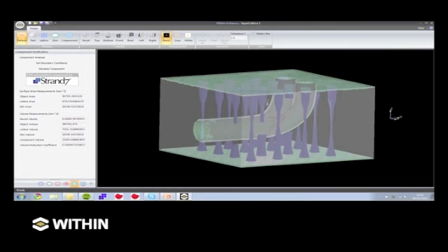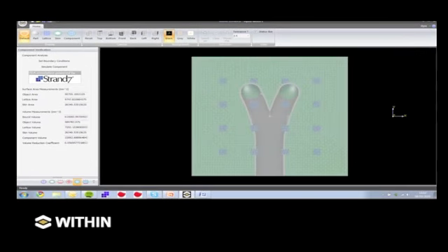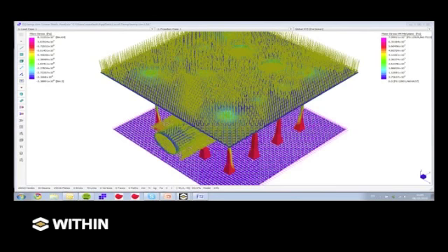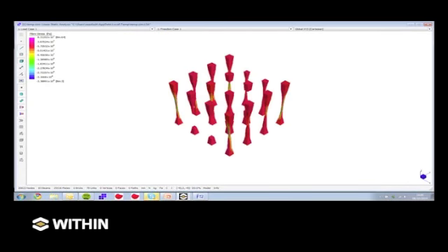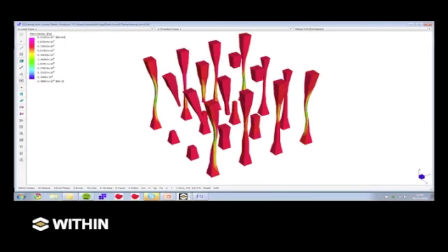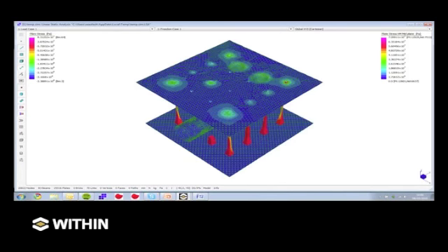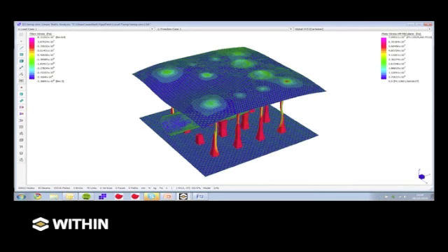So what we do is we can run this through our software, and we say we want to be able to withstand any internal pressure within the pipe, because the pipe is transporting fluids, and we want to ensure that any load along the top surface is also withstood. So here, as I've shown you before, we can simulate the part. You can see the stresses within this internal lattice, and then the software starts designing something that can then be sent to the 3D printer. Now it starts with a small, tight lattice around the tubes to ensure that the tubes themselves are supported, but then starts supporting the top and bottom as well.